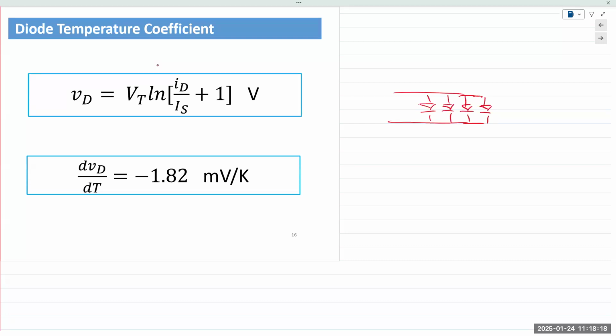So the differing currents are due to the differing saturation currents, IS. And the differing saturation currents are a result of the fabrication process. So again, IS is a result of minority carriers. Also, there is Zener effect and breakdown effect in the reverse bias. So that's a result of the manufacturing process. So the current can change if the voltage remains the same.